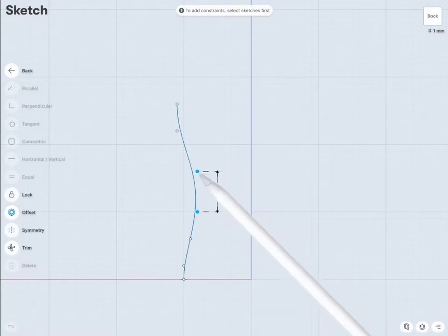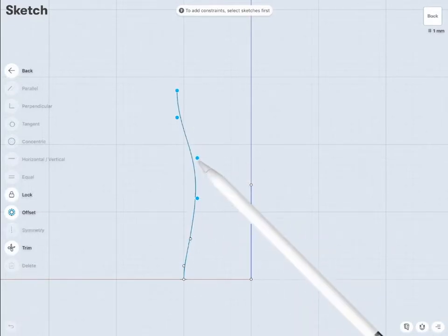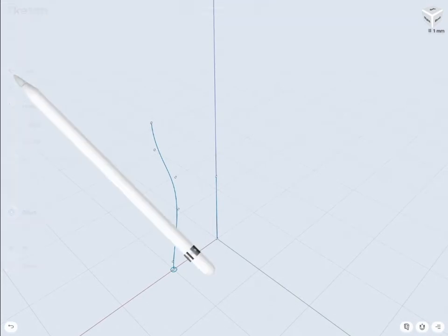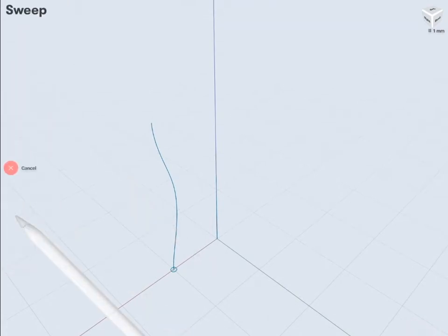The important thing is to create a symmetry line right on the axis. It will help us place the pivot point on some point on that line. That will help us scale symmetrically, or to rotate or make any transformations. So let's use the sweep tool. Now we're going to use a circle as a profile, and the spline we've created as a path to our sweep.